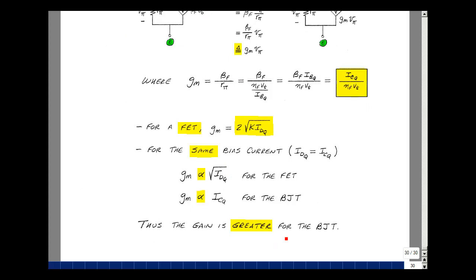When we do IC design, we have to take this into account: the structures we use for biasing a BJT will not work well for having gain with a MOSFET or a JFET amplifier. And this is the analysis of a common source amplifier.